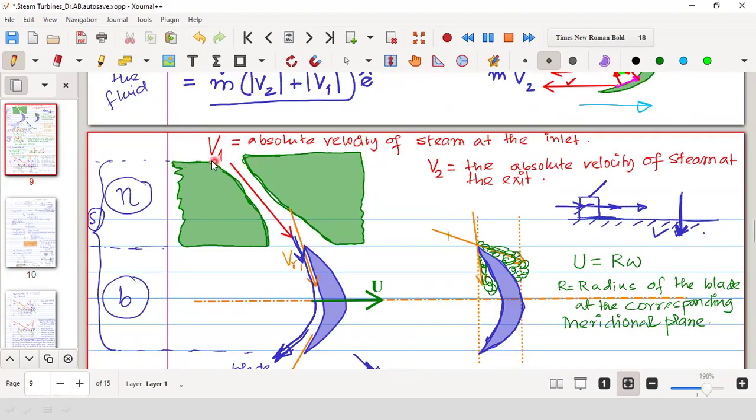So here basically before that there was only the form of enthalpy. Now after that what is happening, that enthalpy drops, and the enthalpy is converted to kinetic energy. So most of the enthalpy drop takes place here. Now therefore the enthalpy is converted into kinetic energy. Now the kinetic energy will change. So you are right, the enthalpy drop will take place only in the nozzle.